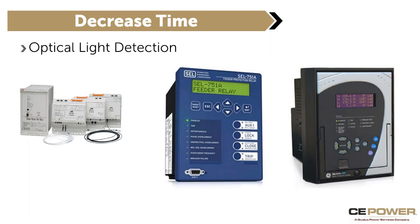There are options for optical light detection, so increasing current and an optical hazard. So in other words, bright light typically would emit in the event of an arc flash, either in the bus compartment or the cable compartment, and is going to trip in milliseconds. So again, if there's work going on in the equipment, or if there is an equipment fault when it's running, opening that circuit in milliseconds is going to do two things.